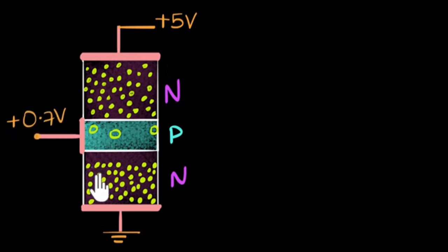And to quickly recall what happens, you see because of the forward bias over here, the P side is connected to the positive, the electrons are emitted from this junction all the way into this junction. And before they have any time to recombine, because of very small amount of holes over here, most of them just get swept across and collected over here. That's because of the voltage, that positive voltage we have supplied over here.